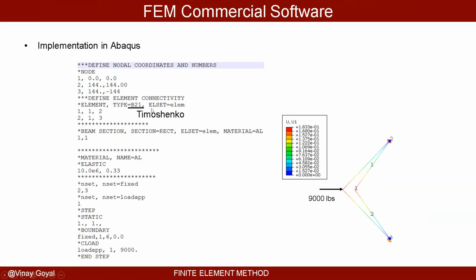But for Timoshenko, all we have to do is change the element type here to get it to work. But very exciting. Timoshenko works for thick beams, also for thin beams if you were to use reduced integration. Timoshenko works for short and long beams, while Euler-Bernoulli beam only works for long beams, but does not work for short beams because it's not formulated in that manner.